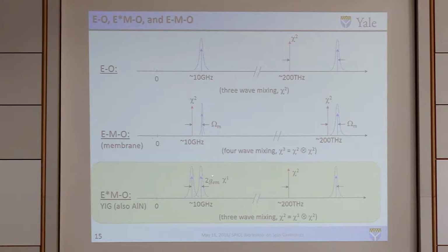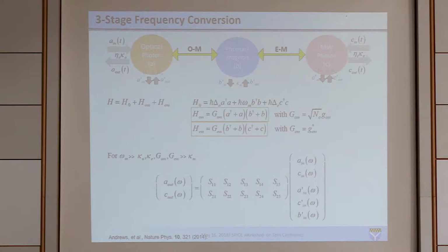With yttrium iron garnet, a little bit different. Here is linear coupling. Here is mode splitting, direct coupling. But essentially, you only need 1 pump. You convert the one with the hybridized mode to the optical mode. With piezoelectric, like the aluminum nitride resonator I showed you earlier, it is the same process. So electro-optic conversion is very easy to model. That's been done in the community.